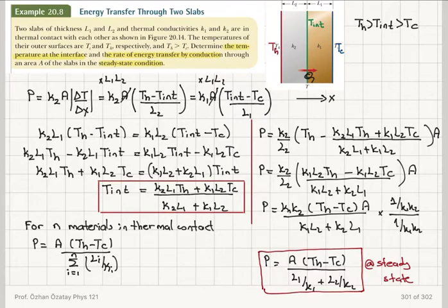That's the generalized law of thermal conduction for many materials. And because this ratio, length divided by kappa, is very important, and we need to add this quantity to find the total value that we have to put at the denominator, L over kappa is called the R value.